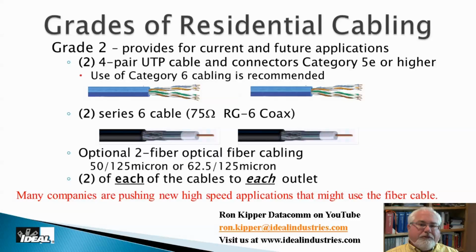You will find applications that require 2 coaxes, and for a lot of years, even today, satellite companies, if there's a DVR or a TiVo type of unit associated with that system, they need a second piece of coax at the outlets in the rooms. And you might be thinking we're trying to sell you lots of wires here, and in a way we are. And I tell people the wires in the walls are the cheap part of the installation. It's what you hook to the darn wires. It gets expensive. But we're going to err on putting lots of wires in walls if we can. And the Cat5e wires, one's phone, one's data, although they can be both phone or both data, but that's kind of the intent. So grade 2 wiring is really what we want you doing and selling to people here.